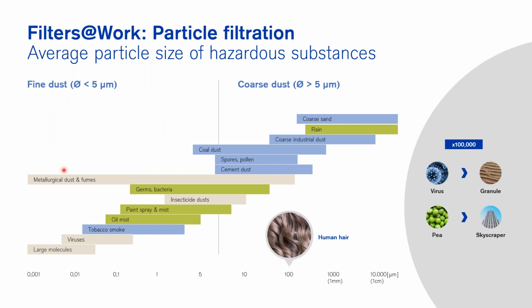But of course, other than just talking about the different standards and the different percentages of total efficiency, what I also need to make known to you is the different particle size and how it actually works. When we look at N95 or even FFP2 at 94 to 95% efficiency, it is focusing on what we call 0.3 micron, which is usually at the baseline of the microns. Why it is focused at 0.3 microns is that it is the most penetrating particle size.